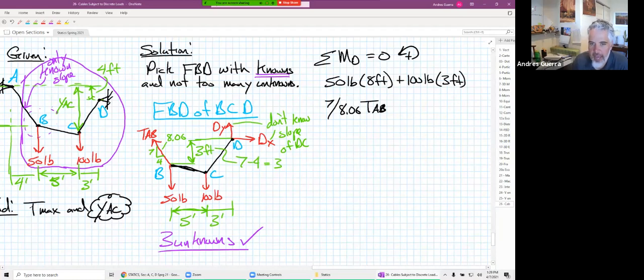And that is going to be multiplied times, let's see, that's the Y component. We could draw it on here, I'll draw it in purple. There's the Y component going up. We have the X component going horizontally. The Y component, the vertical component right there, how far is it from point D? It's 8 feet, so times 8 feet. And then we look, is it negative or positive? It's actually going to cause a negative rotation about point D. So we have a negative there.